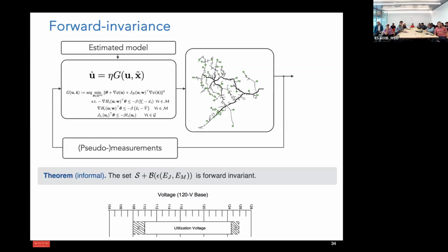Why does it have to be an isolated KKT point? Because the ACOPF is non-convex. So you can have several KKT points, but isolated because here is where the curvature part comes into the picture. I'm looking at the curvature of the cost function around this isolated KKT point, and the curvature has to be at least quadratic, so I can derive these local exponential stability results. If it is not quadratic, I can just get away with practical asymptotic stability.